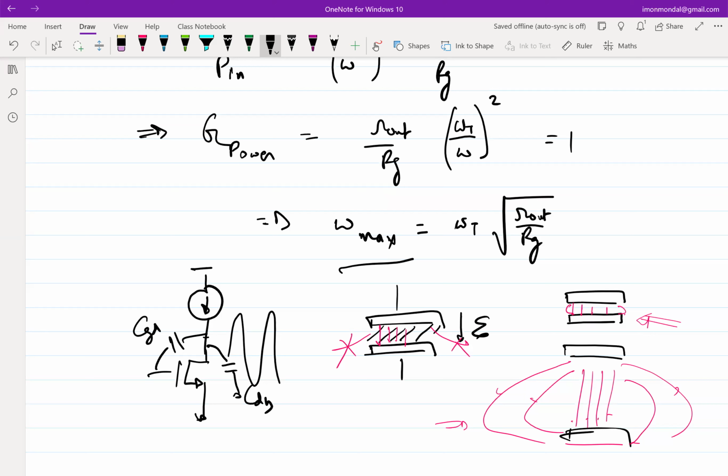Even a 28 nanometer or a 45 nanometer node gives you thick oxide devices, which is equivalent to going back a few technologies. You're going back to 180 nanometer maybe, or 250 nanometer, because they have higher threshold and higher voltage swings available. Again, this is not a generic thing; it is based on how much swing you want. Let's say you want a swing of minus 10 dBm, fine, you can use the low voltage devices. But if you want 20 dBm, then you have a problem.